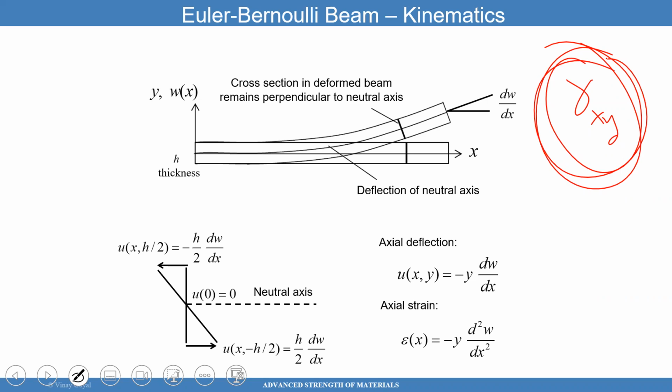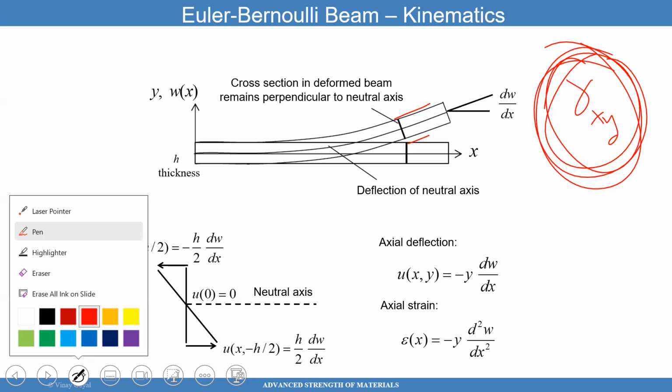And so what we're saying then is that the deformations of the material only depend on the stretching of the outer fiber and inner fiber. Can everybody imagine me taking a beam and bending it? Do you agree that if I bend it as if you're smiling, the top surface will be in compression, the bottom surface will be in tension? The contributions for the deformation of that beam are only solely due to the fact that the beam is stretching the outer fibers and the inner fibers, but none of the shear strain is contributing to it, which is not the case for very thick beams.